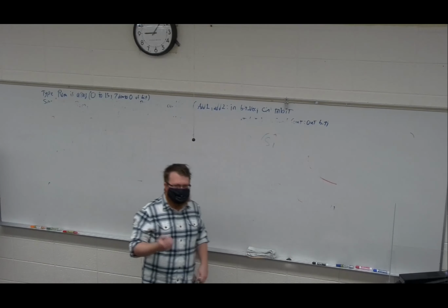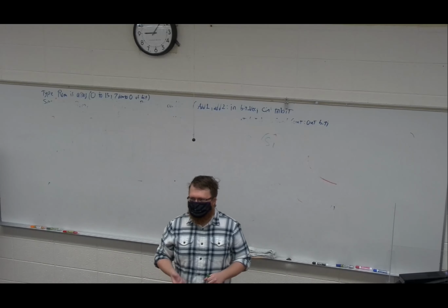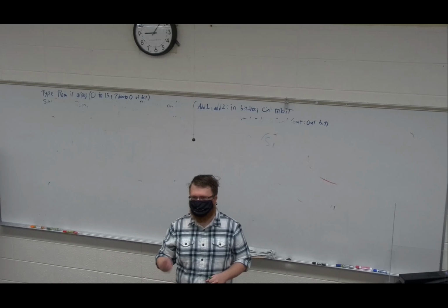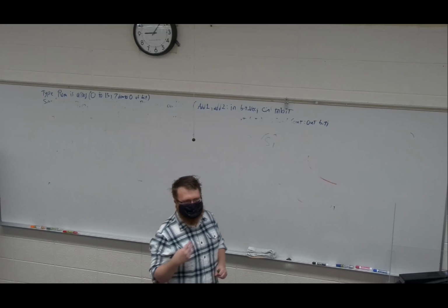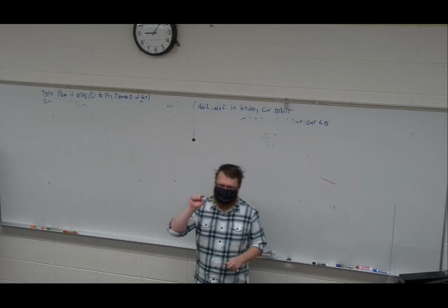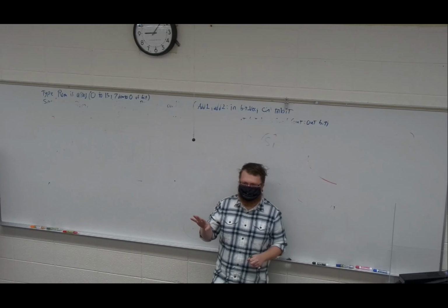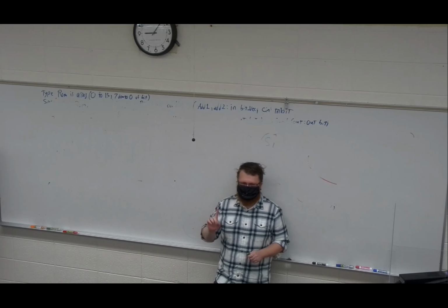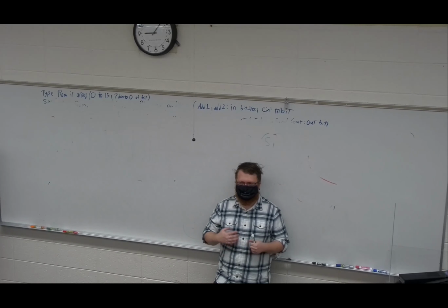If you wanted to test all possible combinations of a 4-bit adder, you would need 2 carry-in states, right? 0 or 1 for carry-in, and then 2 to the 4 for each of the inputs. So that would be 16 iterations of A, 16 iterations of B, and 2 iterations of carry-in. That's 2 times 16 times 16 inputs, which you wouldn't want to write out by hand.